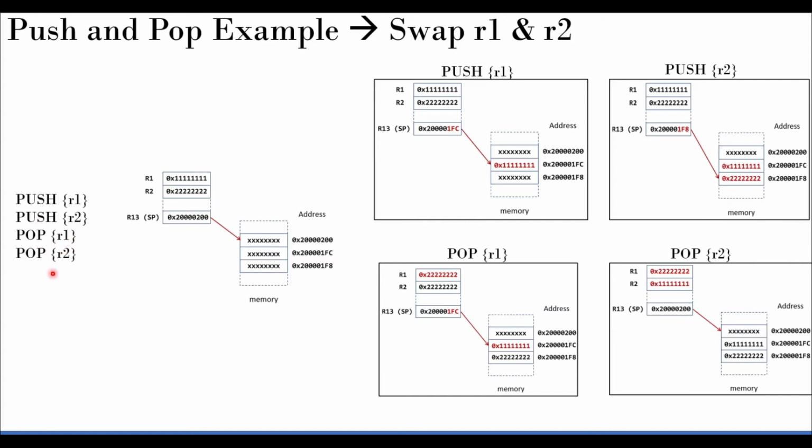Yeah, I think sometimes it's good to make that mistake. So what I'm saying is, the command push R1 R2 will not work, because R2 will be stored first and R1 will be stored second, so that R1 will be ready to get. It will work, but then you have to change the order.